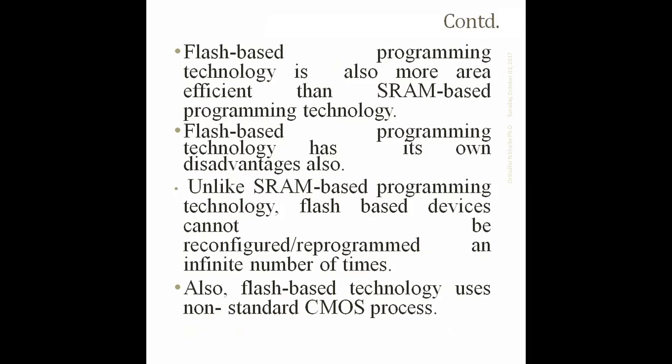Flash-based program technology is also more area efficient than SRAM-based program technology. When compared with an SRAM, the area occupied by flash memory is less, only it is read-only memory. That is the reason it occupies less space: fewer transistors are required. Flash-based technology has its own drawbacks also.